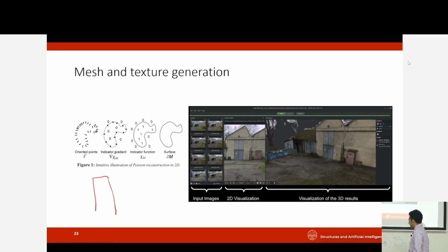So that's a good question. Are there intermediate steps to convert a mesh model to a BIM model? That I would say is an active area of research. People have proposed some automated, some semi-automated processes, and also people usually use it as a reference, because if you have a mesh model, you can import it into Revit, and then you can use a tool called Dynamo where you can create things parametrically, and you can get it to match by visually looking at it.